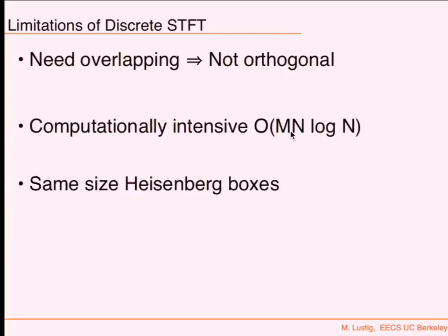Well, if you compute the DFT, what the DFT does is take the sinusoid and make it into two delta functions, or two spikes that are quite large. Way above the noise. It's kind of like a broomstick that will take the signal and put it into one large coefficient. Now it's going to be above the noise. Okay? So now, after you did that, you can do filtering. But you have to do adaptive filtering, because it depends on the signal.